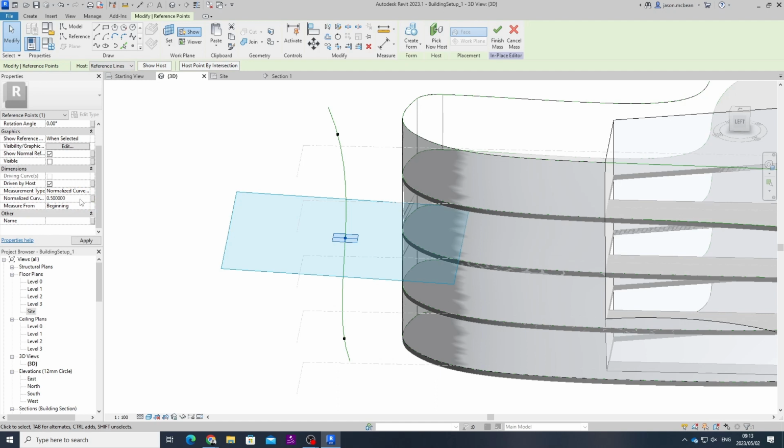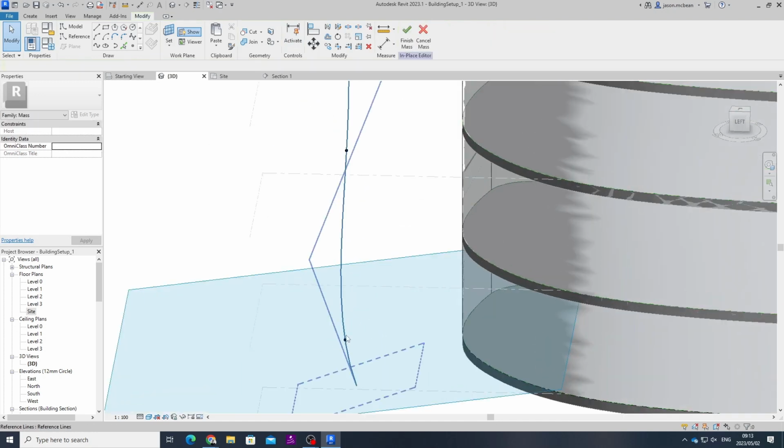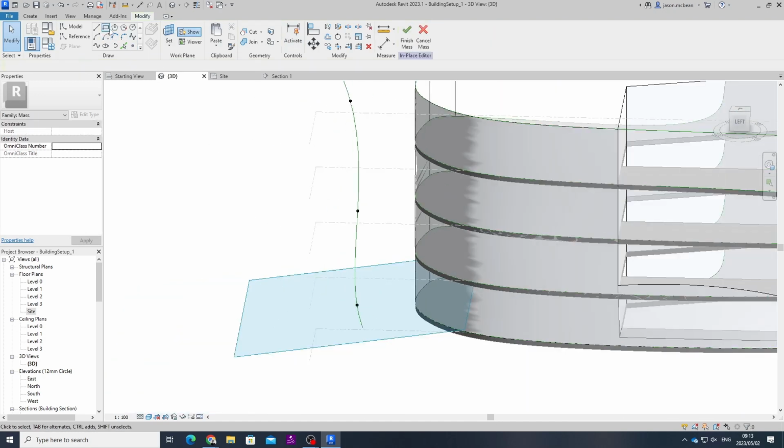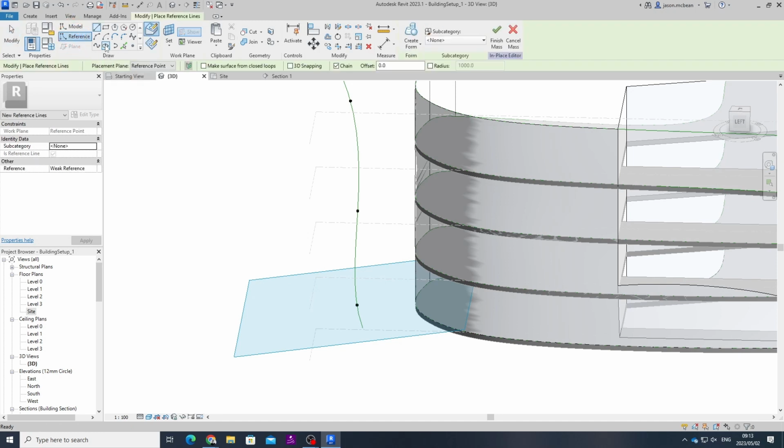You can use distance as well. And this guy, I'm going to make 0.1. It's maths. So you can say if you make it 1/10, 1 divided by 10, you type in. But what's neat about Revit is you can type equals 1 divided by 10. Done. So you can do maths in these. Okay. You can do complex equations as well, by the way. Okay. Cool.